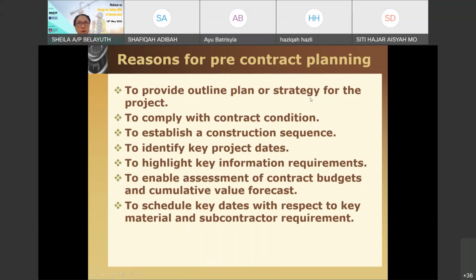Okay, pretty much all construction projects might have gone through some certain delay because of COVID. So reference should be given in the contract condition. Can the extension of time be provided to the contractor because of COVID? Okay, so this should be read. If there is no COVID, what clause can be used to actually say that, okay, this situation is not caused by the contractor. It is caused by force majeure. Okay, so there are external factors that actually cause the delay. So it's important. Hence the contractor, although they sign the thick document, they have to actually understand what the condition allow or do not allow them to do.